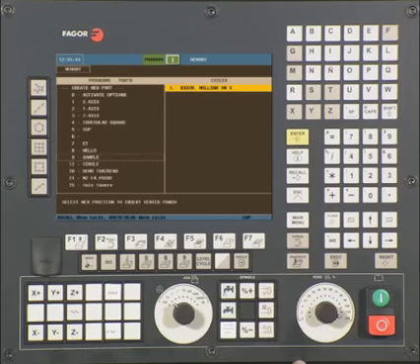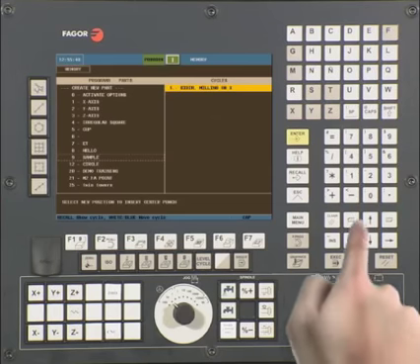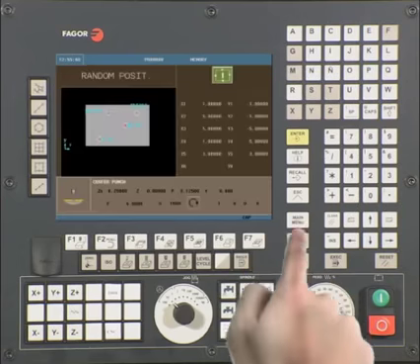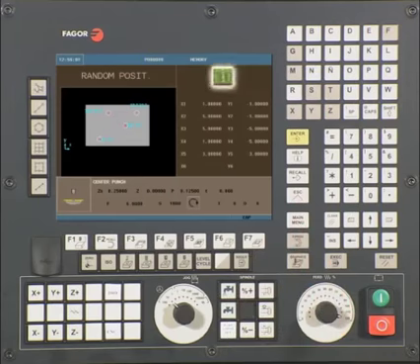Press the P program key. At this point, we should still be under the program we have created. If not, navigate back to the program. Once there, press Enter to insert the center punch cycle and random drilling operation into the program. To execute the cycle, press Escape twice. You now see that there is a cycle start icon at the top of the screen.